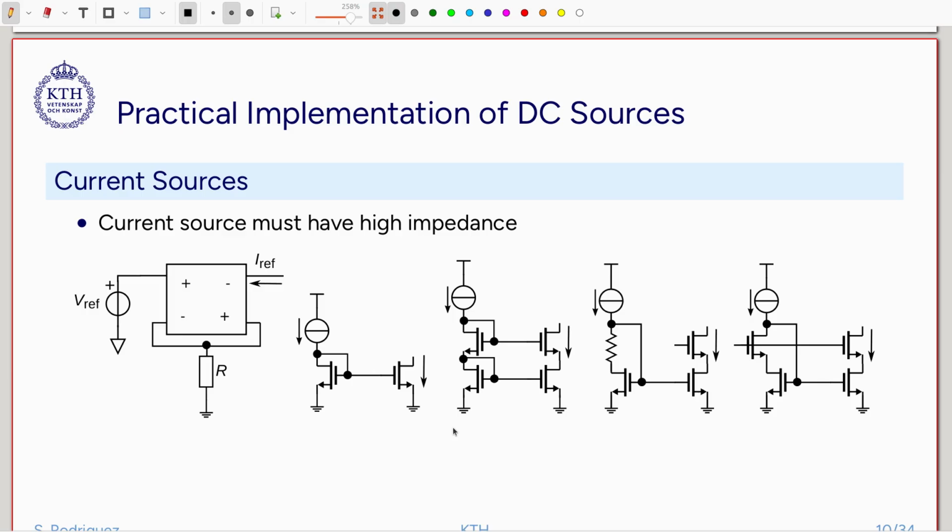This is a bandgap reference, that normally is very stable under different conditions, and then we convert this voltage to a current using the transconductance. So we use this one as a reference current, and then we distribute this very clean reference current around all the analog blocks of our chip.